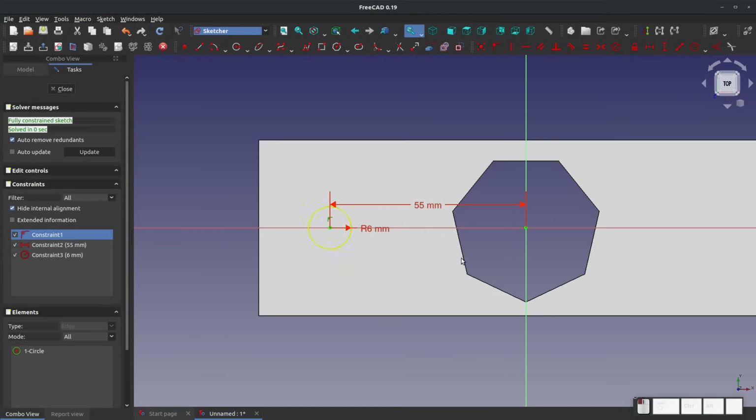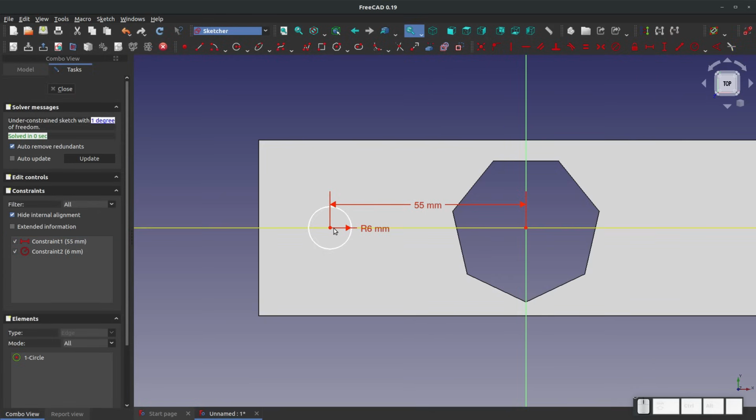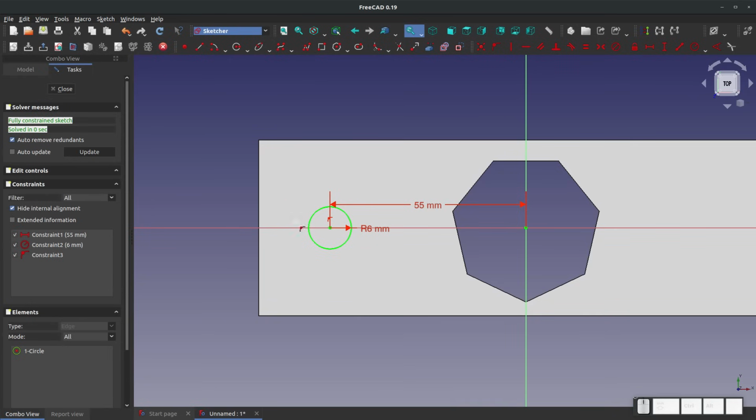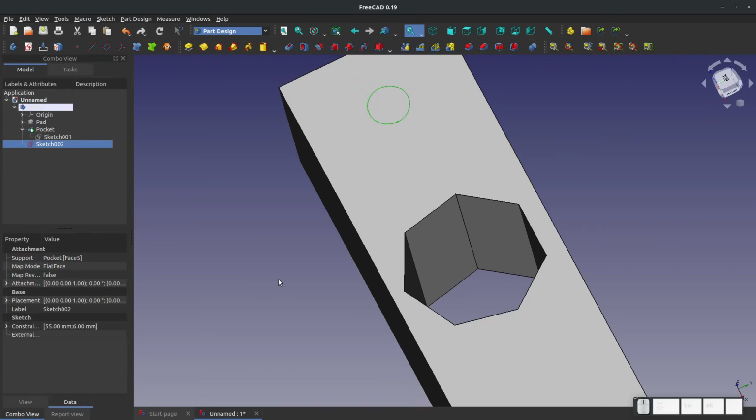One example of something that can go wrong is if you don't have the coincident auto constraint. Maybe you'll say, hey, how come I'm not fully defined? And then when you click and drag, you realize, oh, okay, I need to add either a coincident or a horizontal. So I'll grab my center, grab my line here, and I'm coincident, right? So that's just one example of something that came to mind.